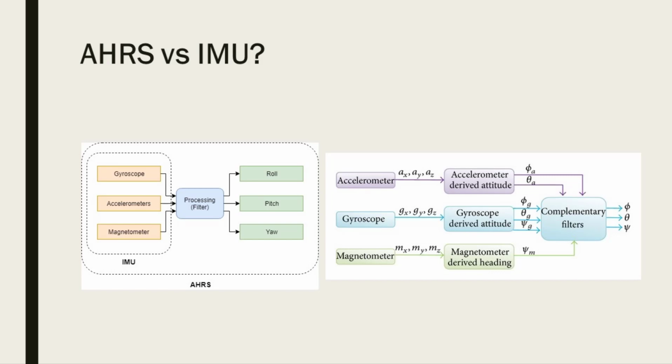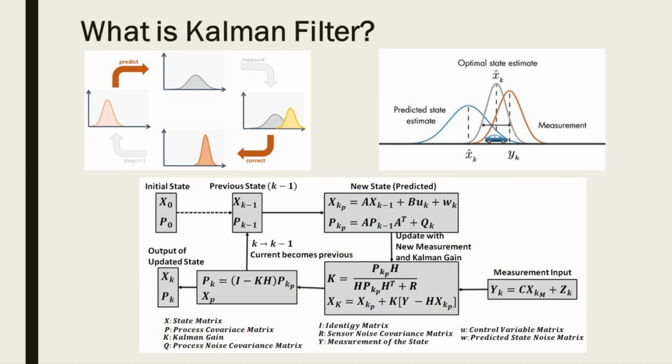You need gyroscope as well. We're going to talk about it more in the continuing of this tutorial. One of the most common ways for estimating the attitude based on sensors outputs is using Kalman filters. Other methods are available such as complementary filter and so on, but Kalman filter is maybe one of the optimum for our purpose. Better ways are available such as extended Kalman filter, but we are going to use the first order linear Kalman filter here.